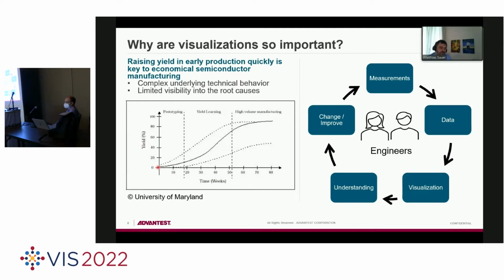So when you start with a few prototypes, when you start your early production, actually just a few percent of the chips are working. It depends from product to product, and on whether you have a new process or not. But for new processes, for really top-notch devices, you can think about starting production with just like 20% yield, which turns into 80% of what you produce being thrown away. Now, that's not a good and viable situation.